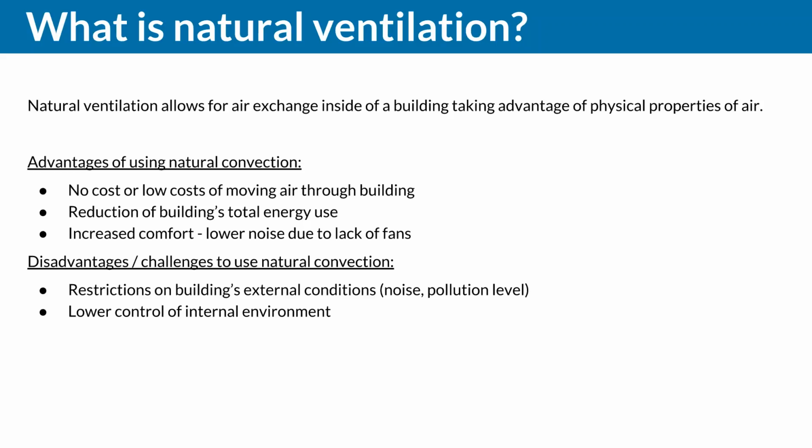And the great thing about natural ventilation is that if we leverage it, it comes with no or very low cost for moving the air through the building, since we are leveraging other energy sources instead of fans, which are used for forced or mechanical ventilation. That can be really helpful, especially when it comes to reducing a building's total energy use.